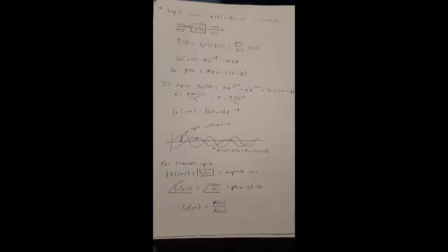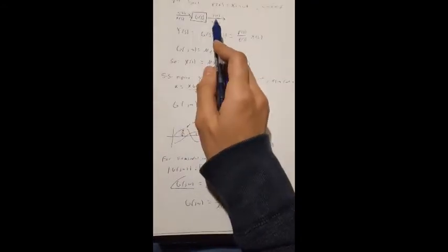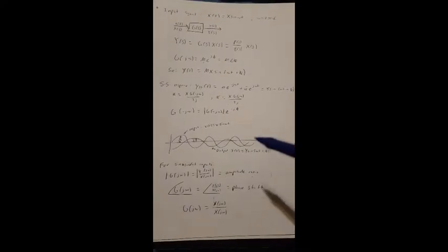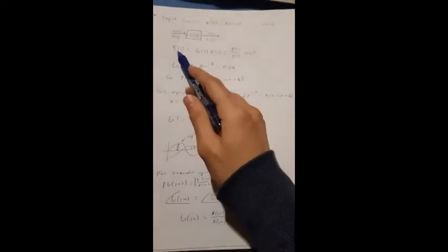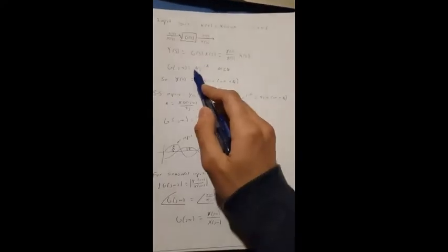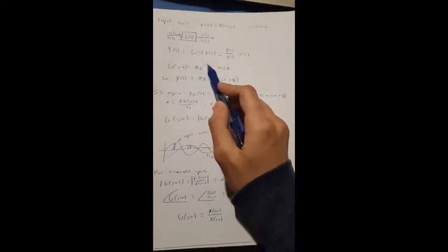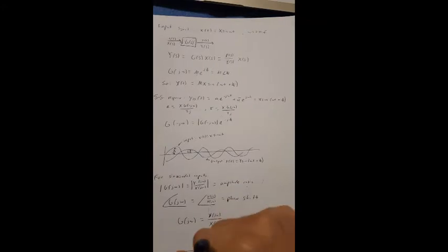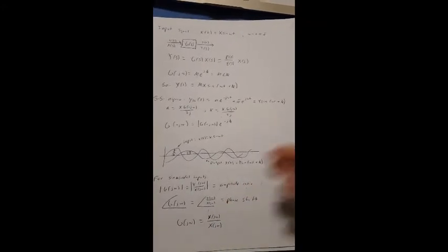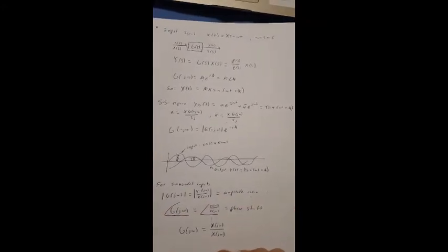So it is important to obtain the steady-state outputs to sinusoidal inputs. We denote the input by x(t) and the output by y(t). The output will be a sinusoidal signal as well, of the same frequency with different magnitude and phase angle. The frequency response can be calculated by replacing s with jω, where M is the amplitude ratio or magnitude, and θ is the phase shift between the input and output. In the frequency response, we vary ω until the entire frequency range of interest is covered.